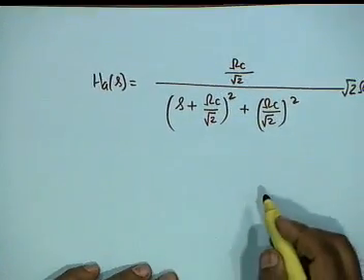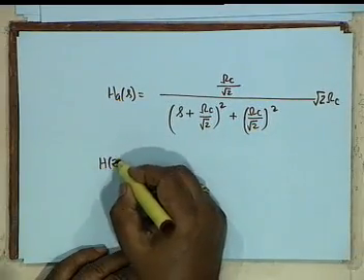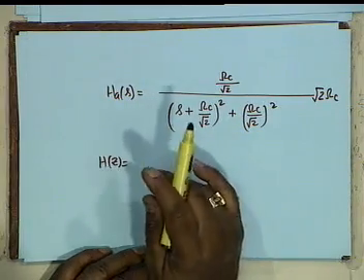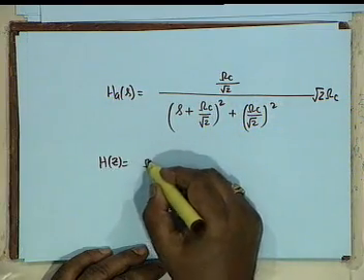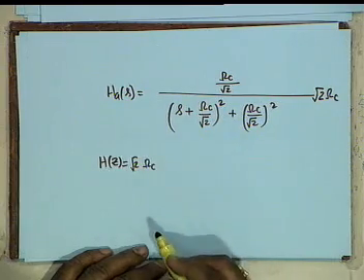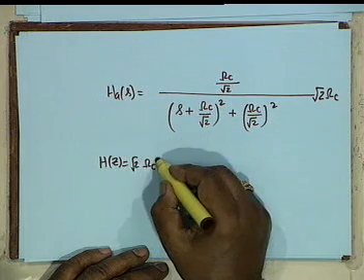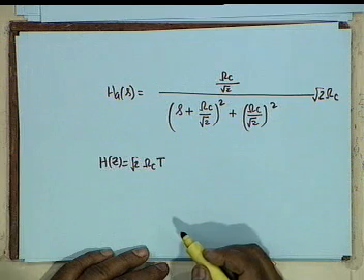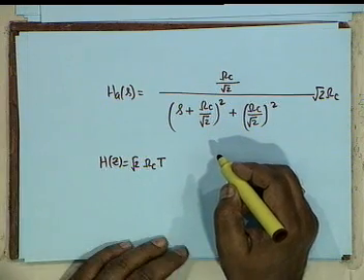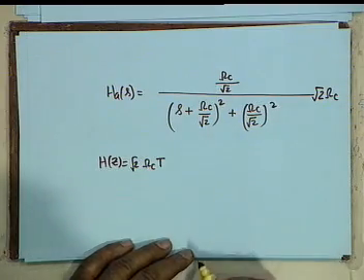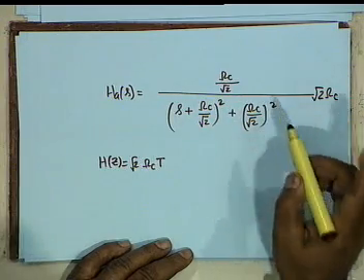Okay. So my digital filter now, capital H of z shall be capital T, this is the point where we introduce this, capital T multiplied by this. So we get root 2. Now we have to multiply by capital T, omega c t. You have to transform this according to that rule.